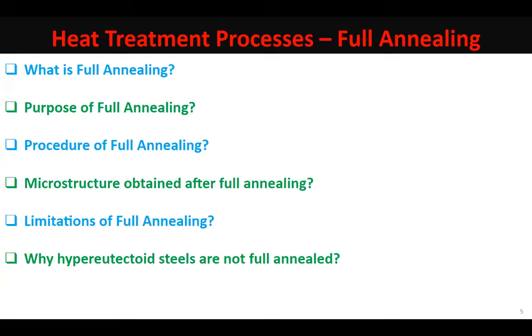Suppose steel was subjected to some welding where it was taken to a very, very high temperature, and as it was cooled, a very bad type of microstructure called Widmanstatten structure formed, a coarse grained structure with all the pro-eutectoid constituent coming at the grain boundaries and also in a mesh type structure within the grains. The structure is called Widmanstatten structure, and it gives very inferior mechanical properties to the steel. Particularly, it ruins the ductility and the toughness of the steel.